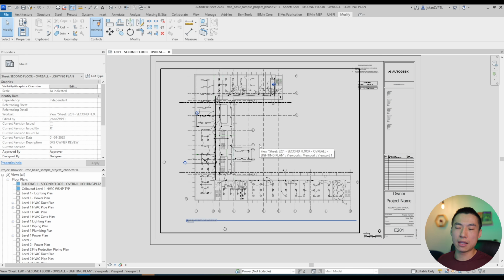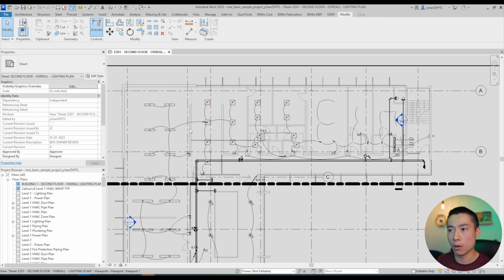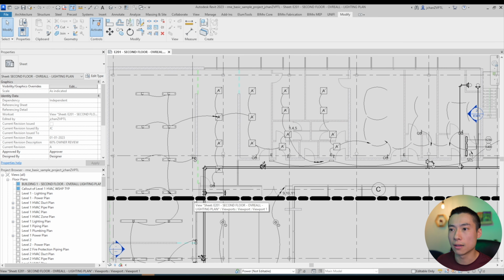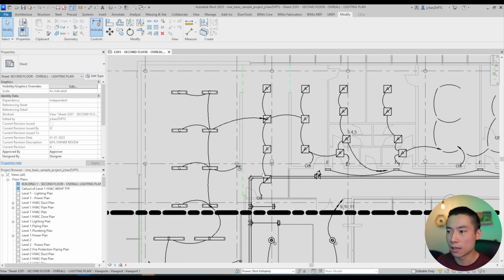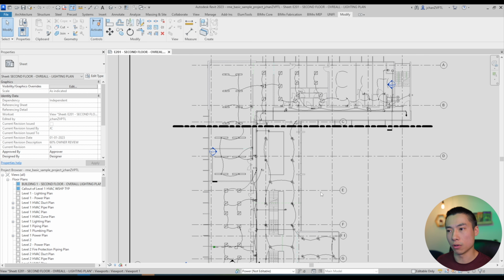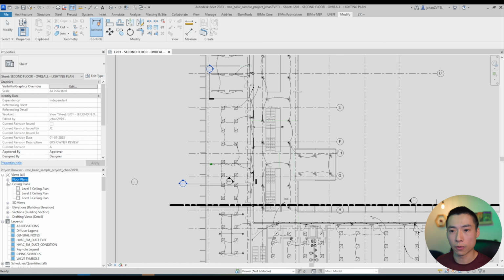All right, so then in the middle, of course, you have your floor plan or your detail or your riser, or the main feature of the drawing. So this is something that you put on here to basically give the contractors and the bidders all the information that you want. So in this case, this is lighting design. So we're showing light fixtures with some wiring. Looks like circuiting's not on here, but there are some switches. So all this information is in the drawing itself, and it changes drastically with what you want to show. So like a power floor plan will look very different from a lighting floor plan.